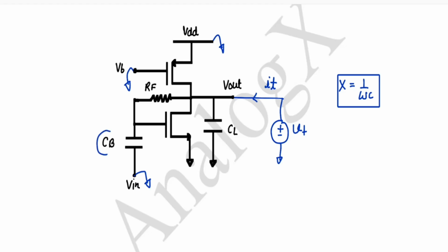Since this value is large and this is small, for a given frequency, this capacitance will offer a low impedance. I want to say that between these two capacitances, CB will be shorted first, and after increasing the frequency much more, then CL will short.